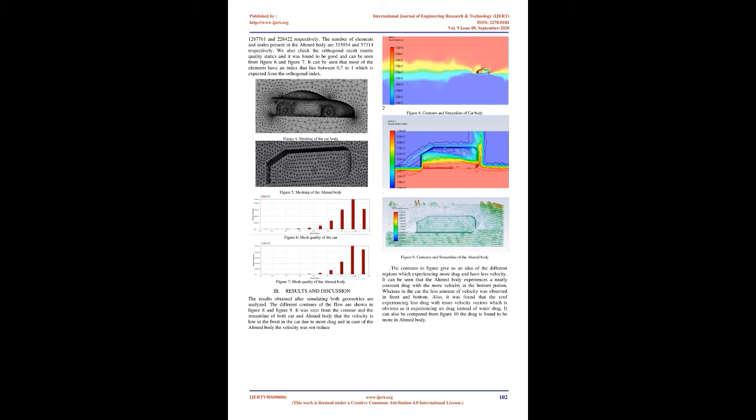2. Methodology. A. Outline. Computational fluid dynamics can be used broadly in the study of aerodynamics as well as hydrodynamics. Many investigations and researches have already been done on drag reduction of vehicles moving in water. This research focuses mainly on a comparative study of the Ahmed body and a general car body moving in the water. The Ahmed body is a generic car body. The airflow around the Ahmed body captures the essential flow features around an automobile and was first defined and characterized in the experimental work of Ahmed 8. Although it has a very simple shape, the Ahmed body allows us to capture characteristic features that are relevant to bodies in the automobile industry.